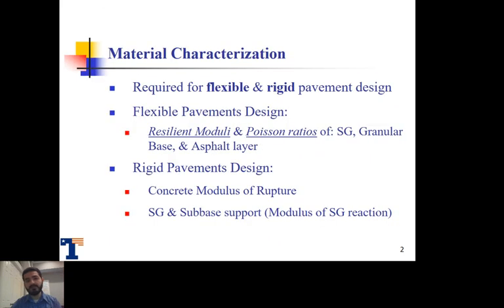So again, it's one of the most required steps that we need to do for any flexible or rigid pavement design. When it comes to flexible pavement design, we need to obtain mainly resilient modulus and Poisson's ratio for the subgrade, which is the soil layer, as well as the granular base. And also we need to get resilient modulus and Poisson's ratio for the asphalt layer.